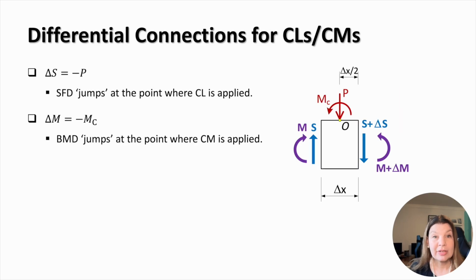We can now summarize the differential relationships for concentrated loads and concentrated moments. Unlike distributed loads, concentrated actions act at a single point rather than continuously over a length of the beam. For this reason, we do not integrate these relationships in the same way we did for distributed loading. Instead, concentrated loads and concentrated moments produce immediate changes or jumps in the internal force diagrams.